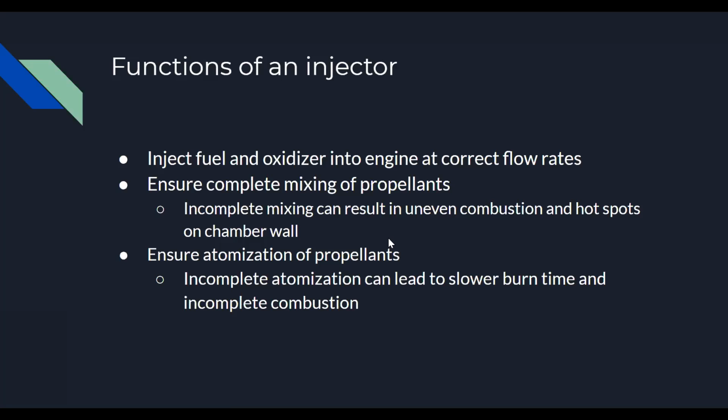That's because that allows more surface area on the droplets, so the reaction time will be faster. If you don't have good atomization of your propellants, you'll have a slower burn time, incomplete combustion, and then your CEA will be off again. So yeah, all important things that the injector has to do.